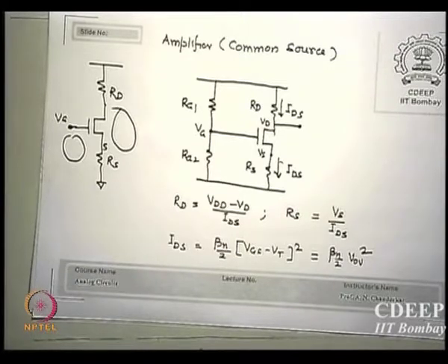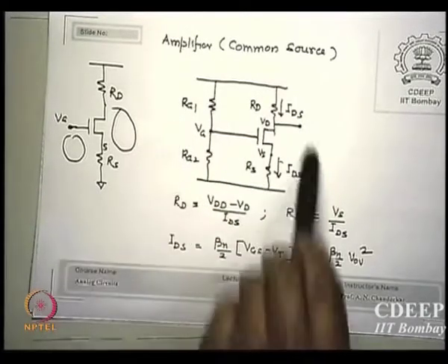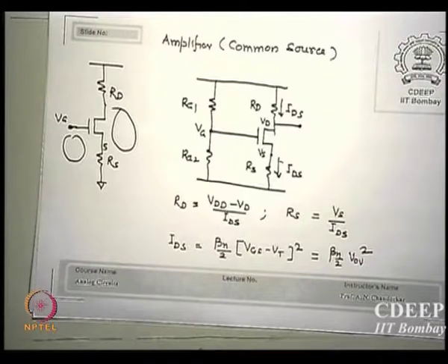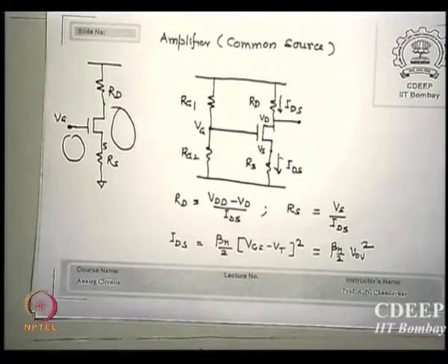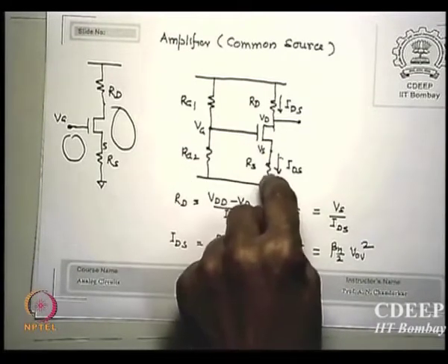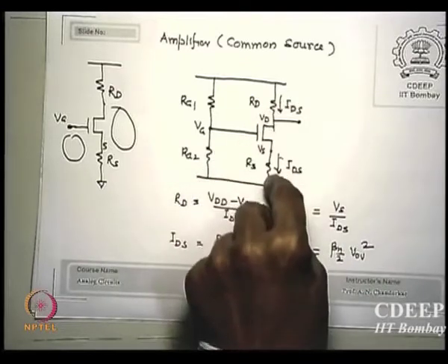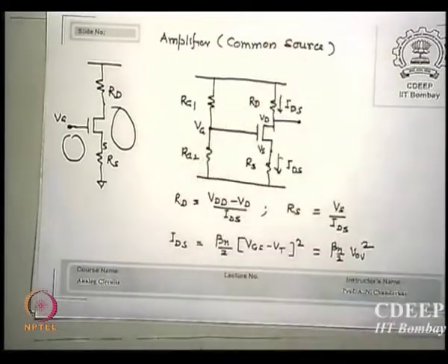So if I have a common source amplifier, biasing will be something of this kind. Do you see it is similar to what we did just now for bipolar? There it was RB1, RB2, here I made it RG1, RG2. There it was RE, here it is RS; this was RC, there it is RD.